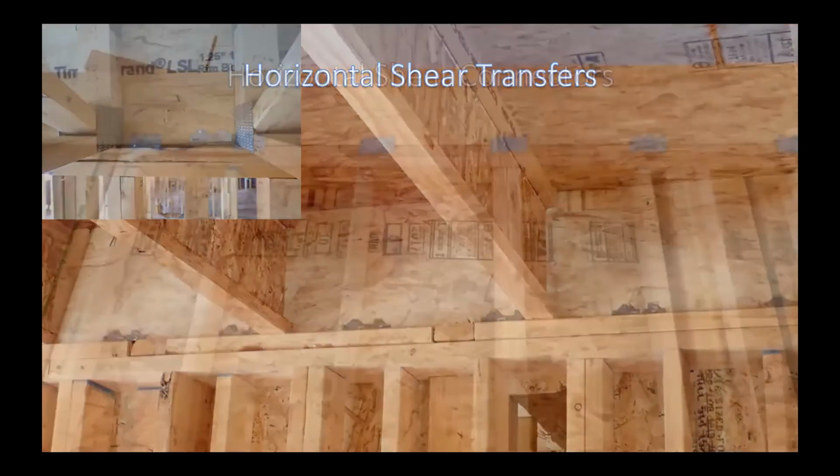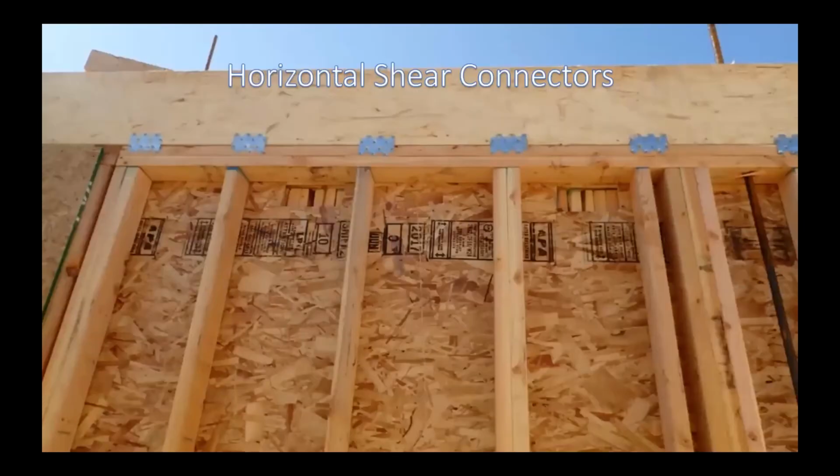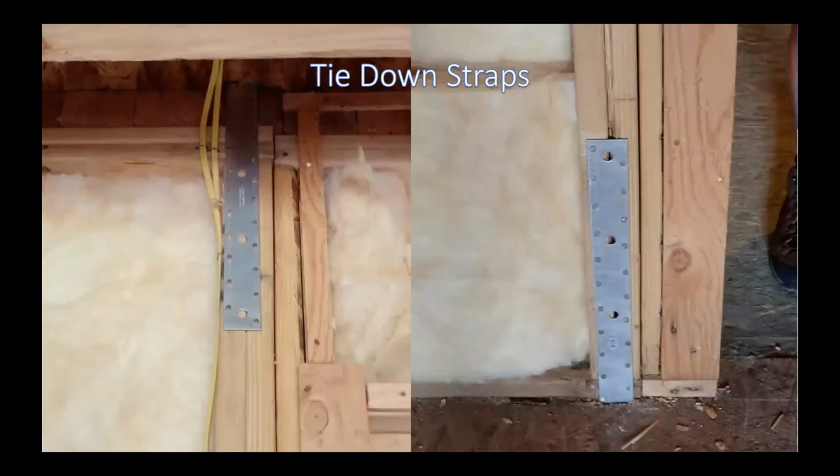A lot of boundary beams and joists would be fixed for the same reasons, using all these horizontal shear connectors to make sure that you have the full shear transfer from floor to floor to floor, from floor to shear wall, and down the 6 stories. Yep, a lot of tie-down strap. Naturally, you want to make sure everything's tied and connected and wrapped.